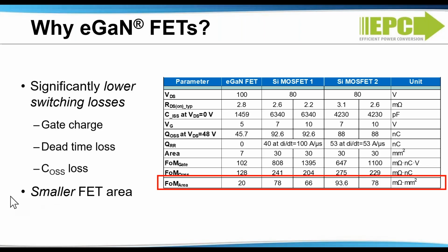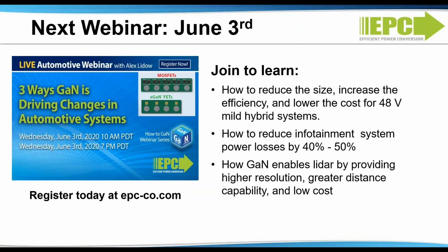In the 48 volt to 20 volt and the 48 volt to 12 volt converter, which component is the major source of loss? So those are two very different questions. In the 48 to 12 volt converter, we're probably talking about an LLC or a buck converter. In the buck converter, the largest component of loss is the inductor, almost always the case. In the LLC, it can be the synchronous rectifiers on the output side.